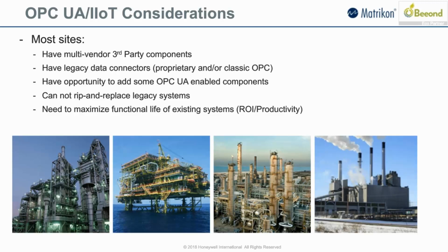So all these things listed here: multi-vendor, third-party components, legacy data connectors, a lot of OPC Classic out there, as I mentioned. OPC UA rip and replace of legacy systems is just not an option. This is actually a major initiative by an organization called the Open Process Automation, led by ExxonMobil, to address this very challenge of moving companies or adopting a standard, and OPC UA being a big part of that allows this interchangeability.